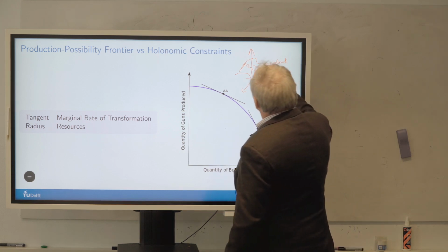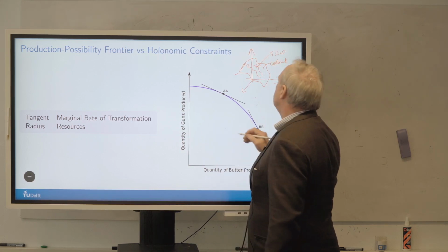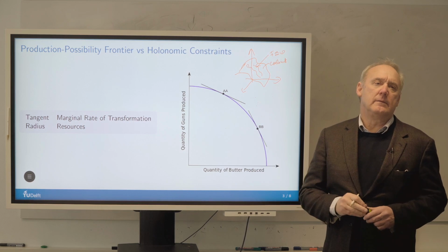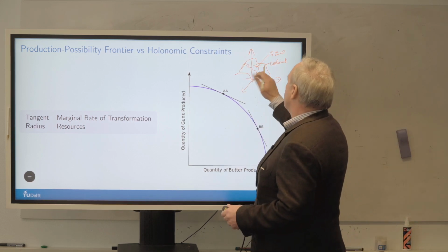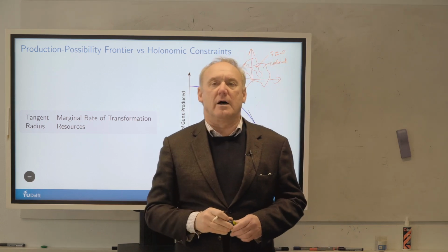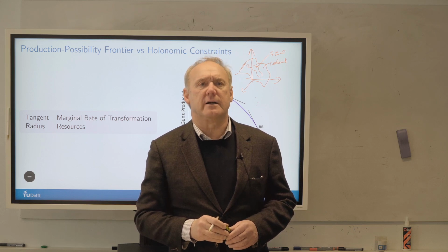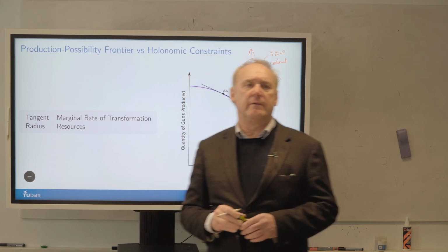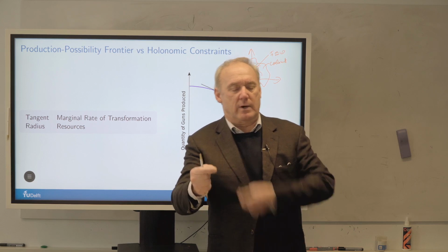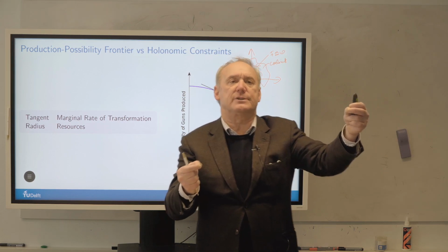And effectively, what happens is there are some forces that are infinitely big, right? That keep it on there. And if you have a constraint like this, where it's just on a submanifold space, this is also called a holonomic constraint. You may have encountered that term in some of your classes. Has anybody heard of this thing called holonomic constraint? Yeah. And so you can have some kind of bob on a wire, and it's just sort of a rod and it's turning, and it can't go further, so it's constrained by the wire to stay on this thing, right?